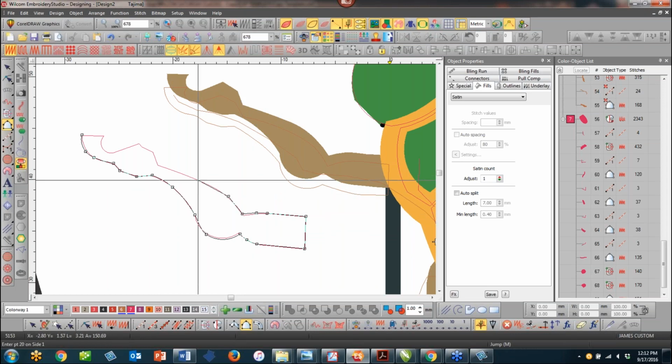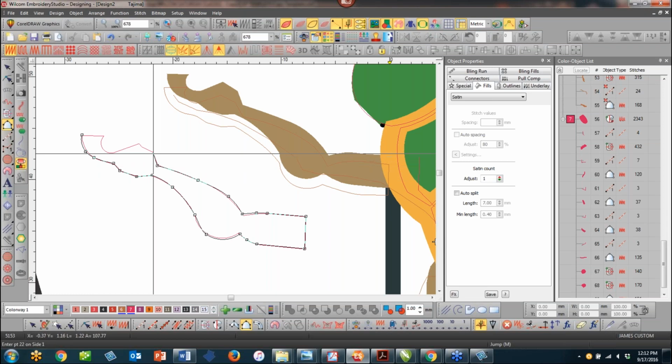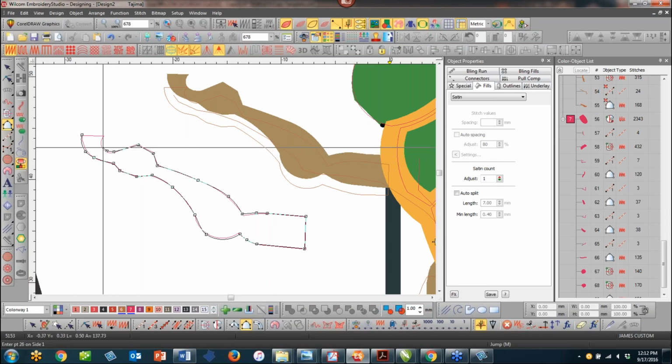And you'll notice also, guys, as you're digitizing, you will eventually, if you have not yet, have your own go-to tool here. And watch what happens. Because now the software actually thinks this is all side A. I'm going to press enter. On the left side of my screen now, it's asking me to enter points for side 2.